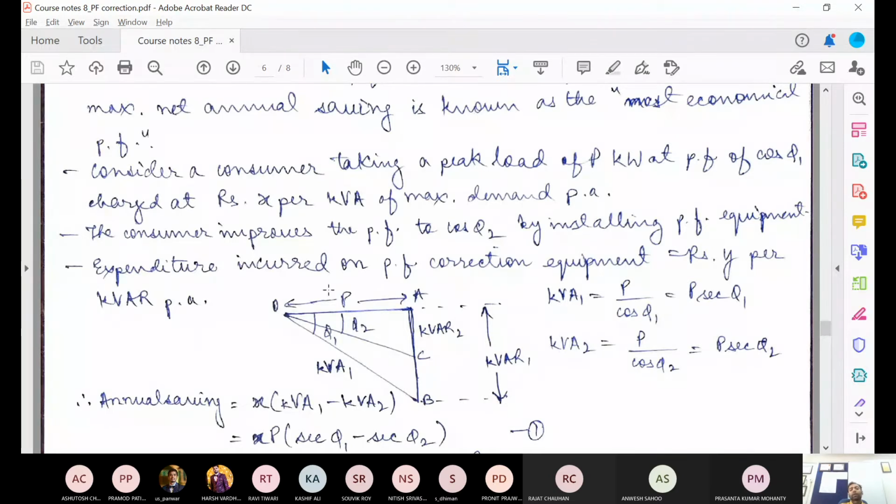Into that domain now, we are saying, let's say your real power demand remains the same. Then what can we do to improve the apparent power is that we can cut down on the reactive power demand. Because as we have discussed, this reactive power is not actually being consumed anywhere. It is not producing any useful work output. It is just circulating in the circuit and consuming some of your current carrying capacity.